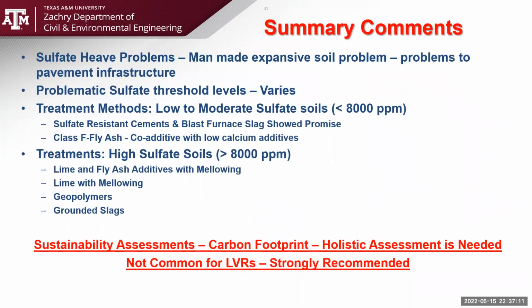With that, I think I have 20 minutes. I may be going a little bit more, but I would like to conclude my talk with the sulfate heave problem. Again, there are a lot of man-made problems. Particularly if you have high gypsum in the soil, you must screen the soils as part of the geotechnical investigation to see whether we have sulfates. Try to do more thorough sampling to figure out if we have sulfate pockets, because that's very important. It's easy to miss them.